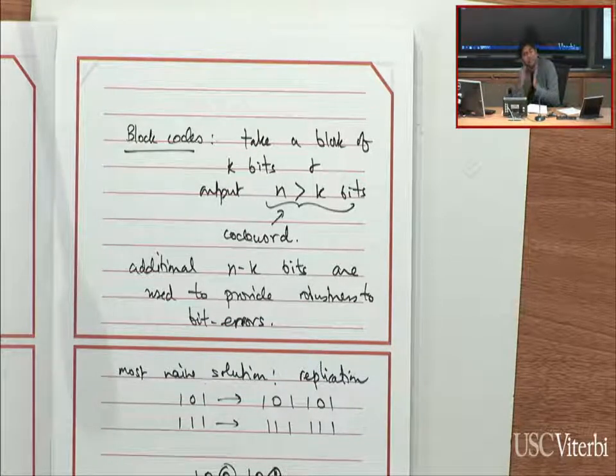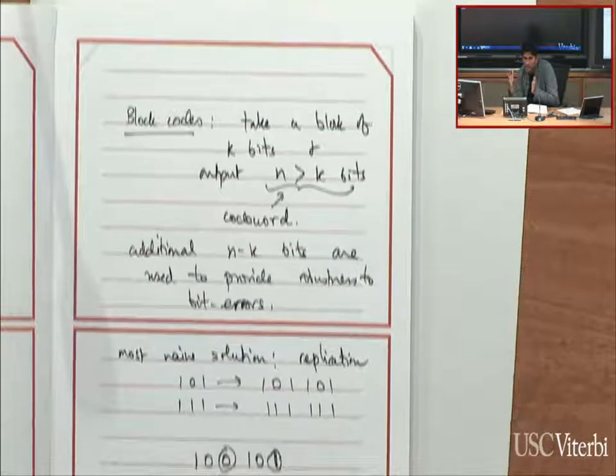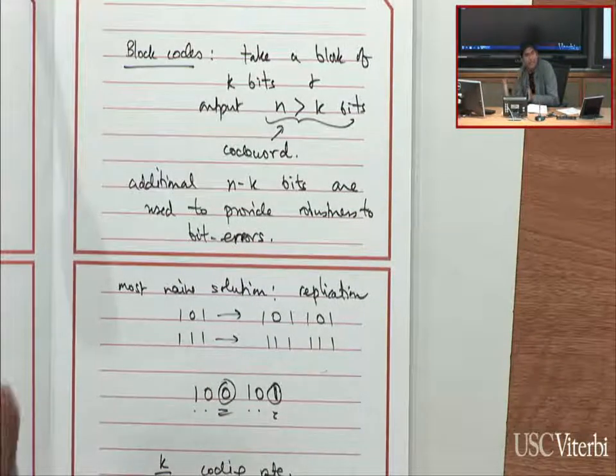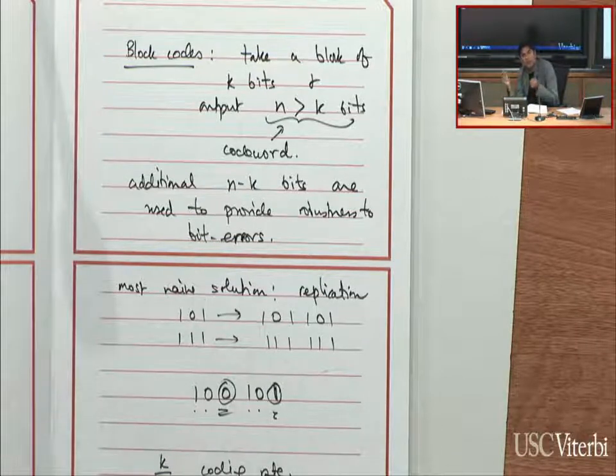At the receiver end, you have to receive that code word, run it through the decoder, and then you got your bits, right? That works well for packetized communications when the block length is the same as the packet length. So you can take the entire packet, encode it into a code word, put that code word in your packet and send it out.